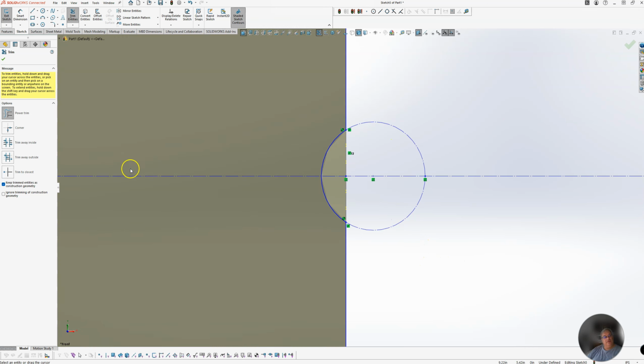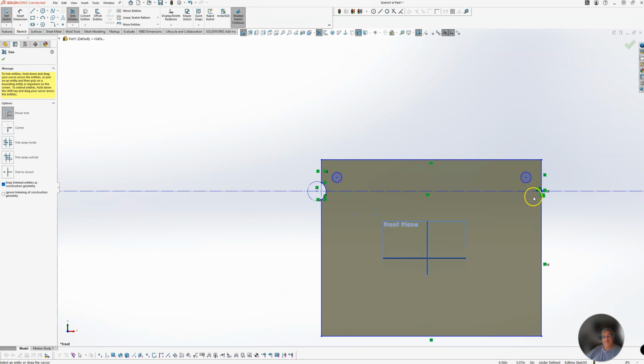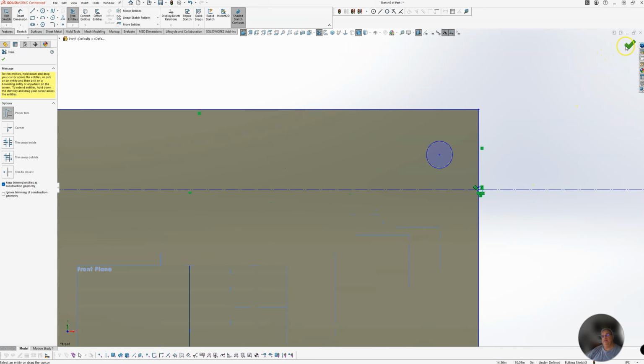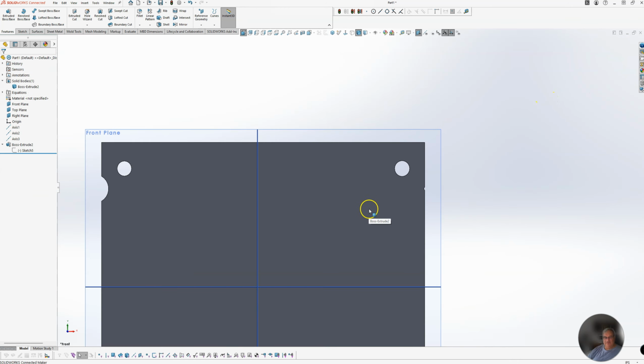That's why you need to really know your tools, because that's why you'd use an infinite line. The only caveat to the infinite line, and to me it's a huge thing that SolidWorks has never tried to fix, is if you want to show your dimensions in your drawing, which I highly recommend. And so you'll argue with that, and again, I don't care. You can do whatever you want. But I just wanted to show that in the line command.